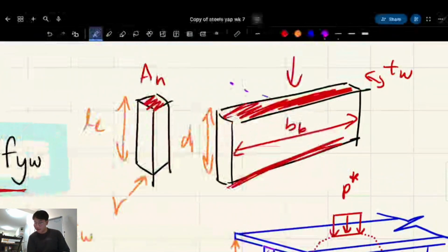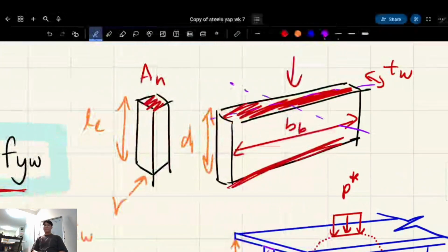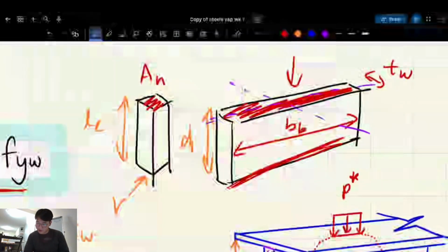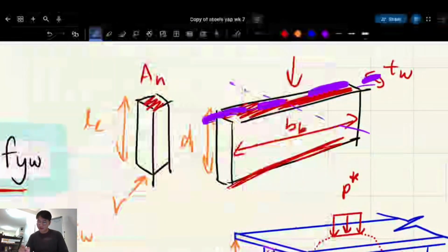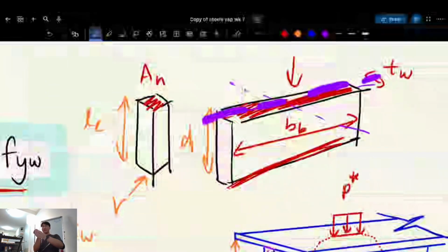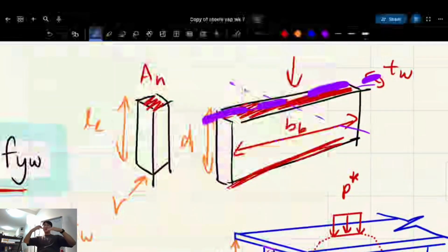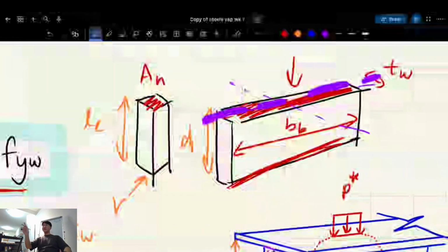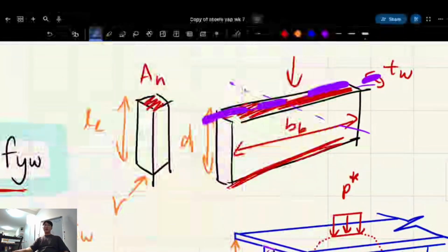So would it bend this way? Direction 1 that I just drew, or direction 2? The directions were lagged. Oh, direction 2. I'm going to redraw it bigger. Side to side, direction 2, right? Yeah, that's the way it's going to buckle. There's no way it buckles the other way, basically. So we don't have to do a single check. We don't have to do RX, RY, that kind of thing.